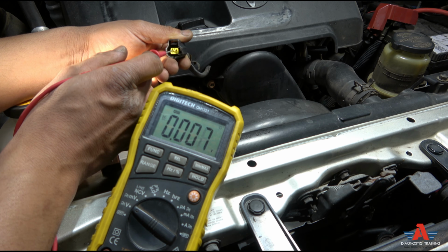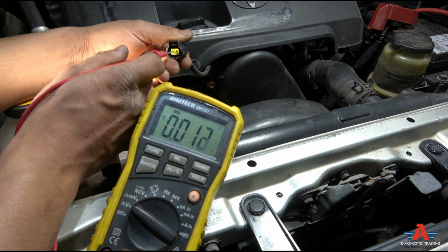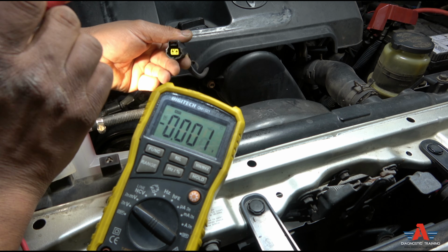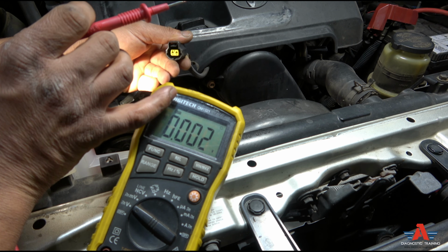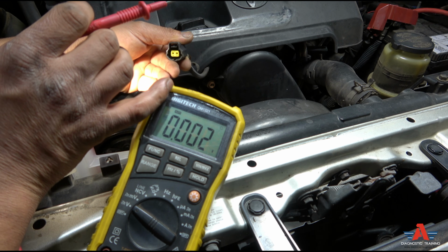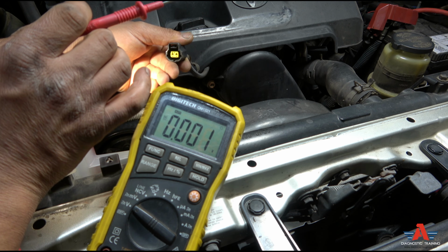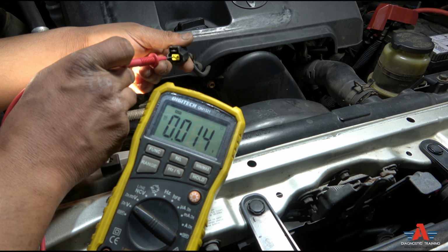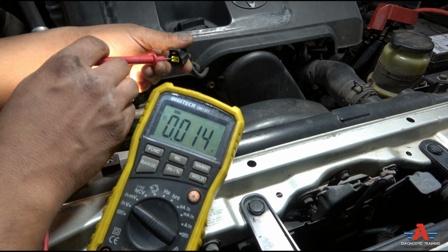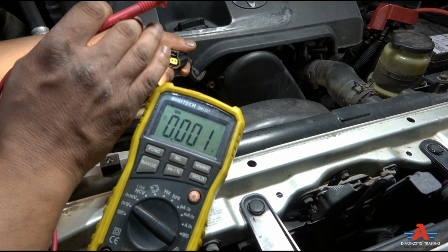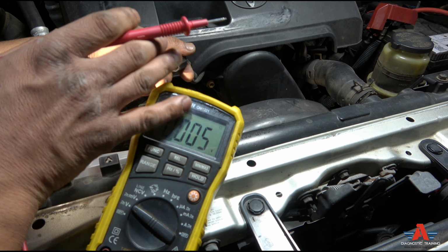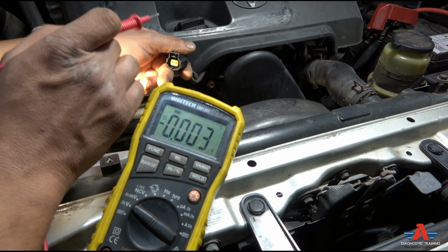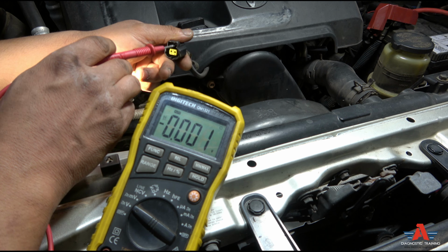Earth, right? So now, sometimes the multimeter can lie. See, right now I'm not touching anything and it's showing me 0.1, 0.001 volt and all that. But if I put it there, even if there's an earth, it's still going to show me numbers around 0 volt. Okay, if you've got experience, you can tell by those decimal voltage readings if there's earth or not.